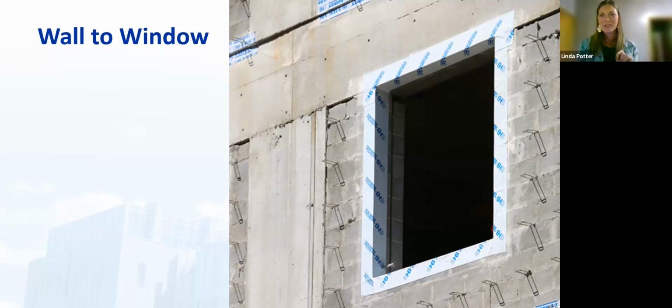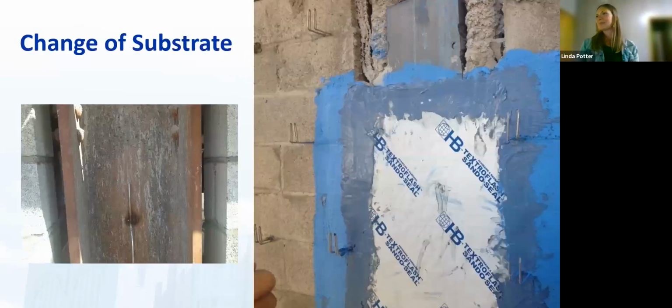The rule of thumb is 3 in, 3 out. So 3 inches around a penetration, 3 inches on either side of a control joint, 3 inches inside a window, 3 inches outside of a window. That tends to be the industry standard norm of what you're going to want to see, so that we've got this whole thing wrapped like a present.